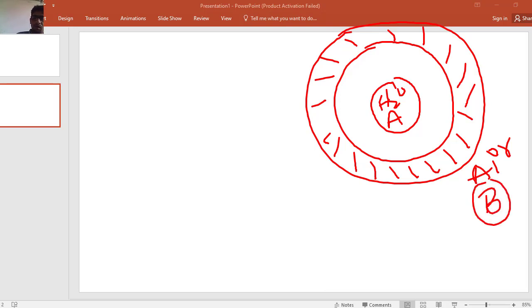The water is non-stationary and it is diffusing into the air molecules around the water droplet. So there is also another assumption that component A is diffusing into non-diffusing component B. The very good assumption is that component A, the water molecule, is diffusing into the air molecule, while the air molecule is not diffusing into the water.